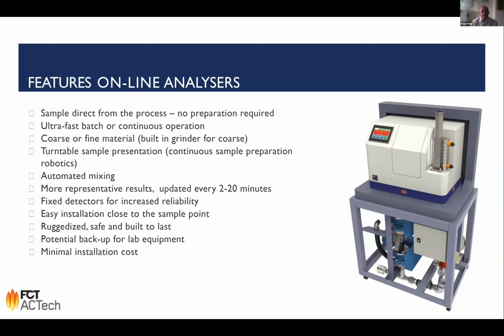The system itself is self-contained, so it requires only a 1000 watt power connection. And we can report the results every 1, 2, 10, 20 minutes, depending on your needs and on the specific applications. Inside the system, the only thing which is moving is the sample material and the supporting equipment to move the sample through the analyzer. All the analytical components are in fixed positions. So we use semiconductor-based detectors, and this increases the reliability.